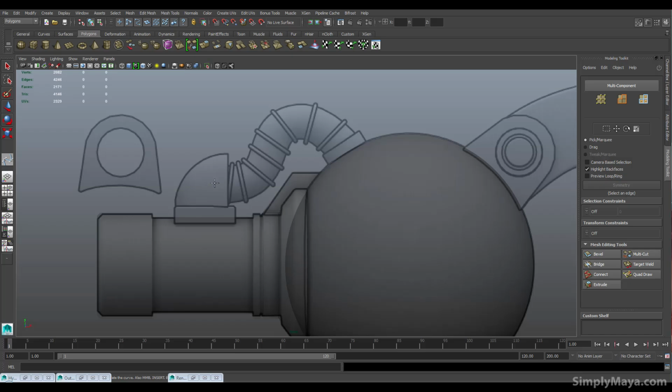So we start by left mouse clicking to put down the first point, and then we want the second point, the third point, and the fourth point. So this has given us something that now doesn't look much like a curve. But if we go in and hold Control and left shift, and then come over the dot, hold the mouse button down, you'll see it gives me a curve handle. Very similar to the pen tool in Photoshop. So I can now just go around and curve these out until they kind of match the center of my curve point here.